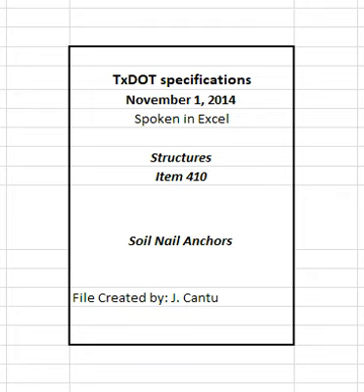Use a reaction system as outlined in section 410.4.4.1, Verification tests. Follow proof nail loading sequence outlined for section 410.4.4.1, Verification tests, except use the required proof load stated on the plans. Proof test nail acceptance criteria.